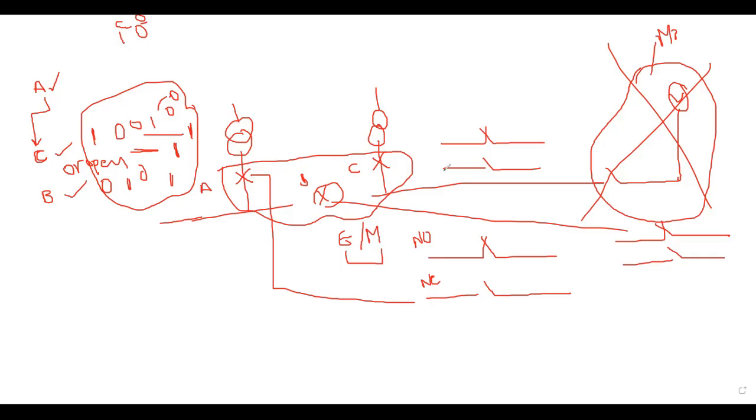So I have to implement the OR gate between this C and B. I will take the status of the C, and the status of this NO or NC, whatever it may be, and I will create an OR gate, and this signal I will use here. If any one signal comes in, meaning the flag rises to 1, then this breaker will be closed. This can be done digitally, or you can develop it with hard wiring. You can develop it with hard wiring also.